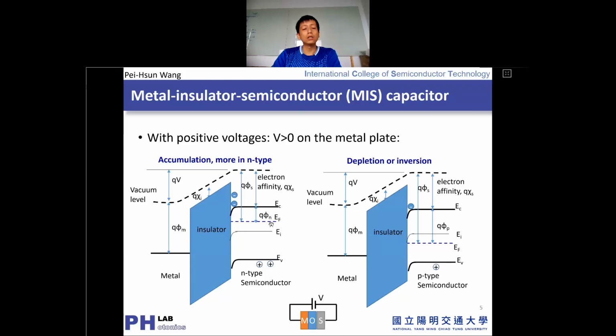So if you look at the Fermi level within the initial doping concentration, you get the difference between the conduction band and the Fermi level. And we can note it as phi n. And these phi n's will be smaller along the surface. That means your Fermi level approaches the conduction band and moves upwards from the intrinsic level. That means you accumulate, or seem to effectively have, more dopant concentration. And these dopants will be N-type, or you can say it is electron.